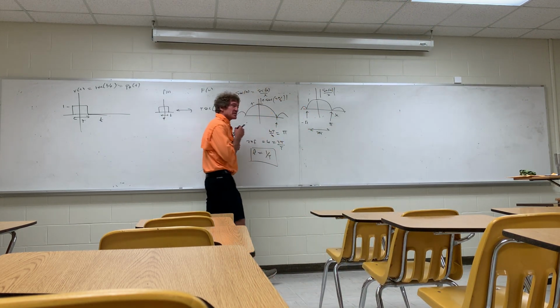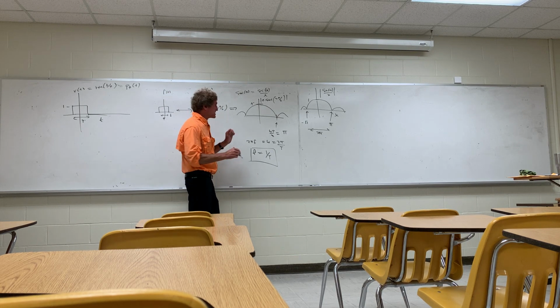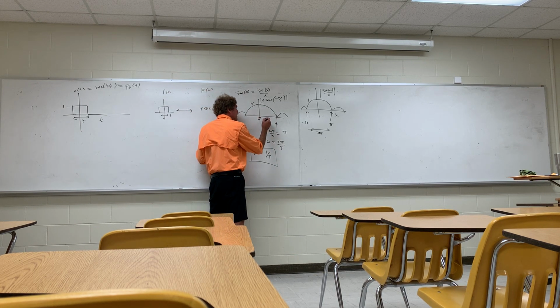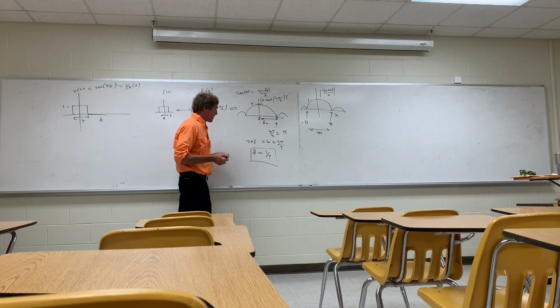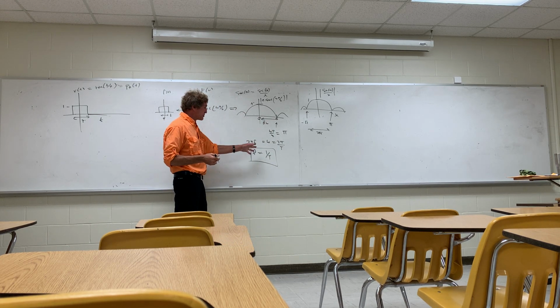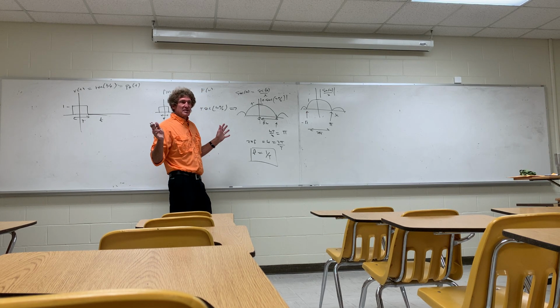If you look at this for a second, just to understand something, this is 0. The bandwidth itself would be, to the first 0, about 1 over tau. In Dr. Wentworth's book, he puts it at 0.5 over tau, and I'll tell you why. But bandwidth is kind of a mysterious thing.